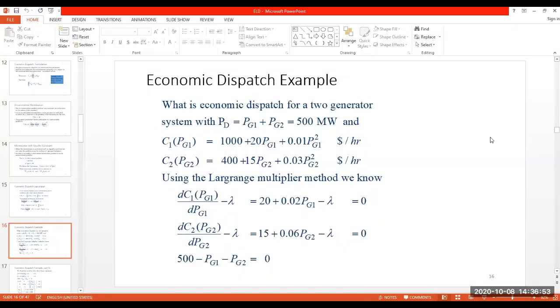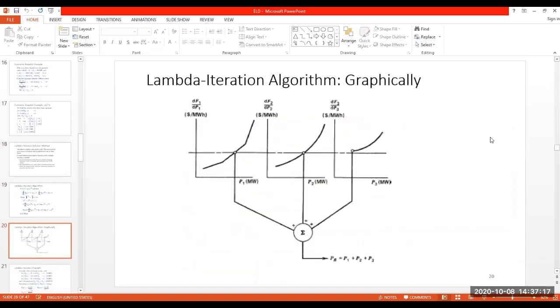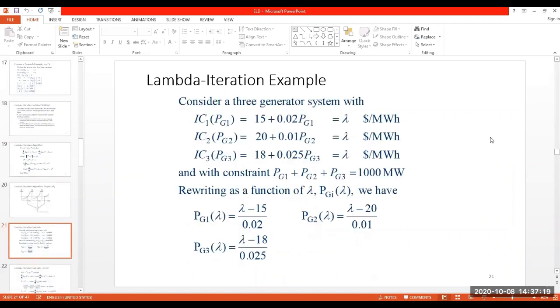Okay, thank you. So we have been going through some constrained and unconstrained optimization theory and associated simple examples, and then application of those techniques in economic load dispatch problem solution. The last topic that we covered was related to the Karush-Kohn-Tucker condition, that is, in short, KKT condition, which basically helps in solving optimization problems with inequality constraints.